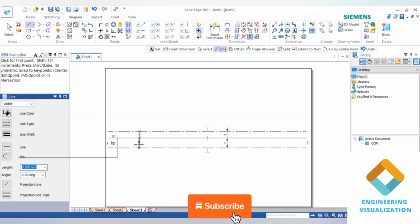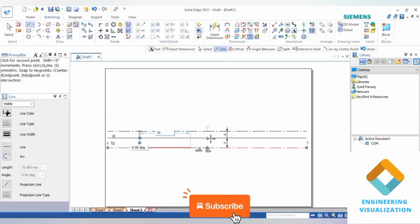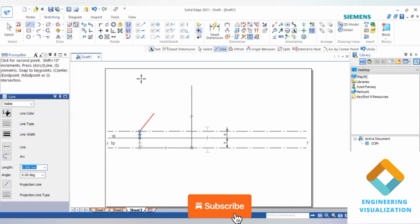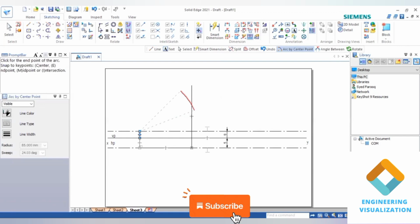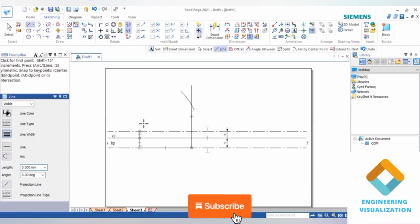true length. First I'll be taking this apparent length in top view, okay, giving 75. So from this end I'll be drawing a vertical straight line. So from this end I'll be measuring for length of true length we have to give. Okay, go to arc by center, give true length 85 and cut the arc. Okay, because apparent length when it is rotated and projected we get the true length here. Okay, now you join from this end point to here.